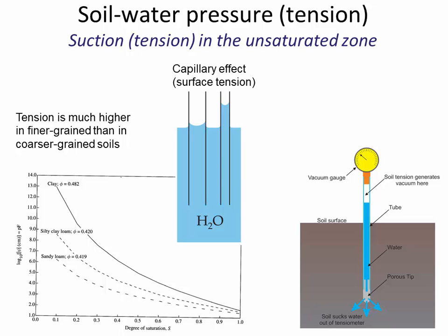there's more infiltration at the beginning of a rainstorm because the soil is going to be sucking the water down. The soil is more hungry for moisture. And it's not that the soil has a brain and the soil is feeling hungry. It's just that there is more tension because the voids are empty.